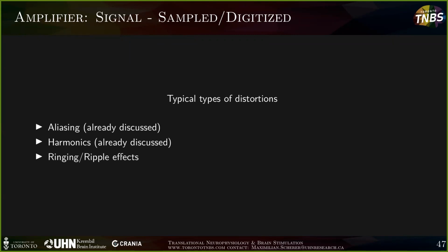A ripple effect is if you apply some filtering, as we will later see, or some other digital signal processing method. If you're looking purely at the frequency domain of your signal and not at all at what happens in the time domain, it may be that, let's say you apply a super strong filter, your signal becomes literally rippled. That will create an artifact in your data that you will have difficulties getting rid of, if at all. So you have to be careful about that.